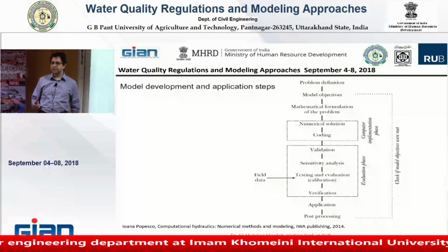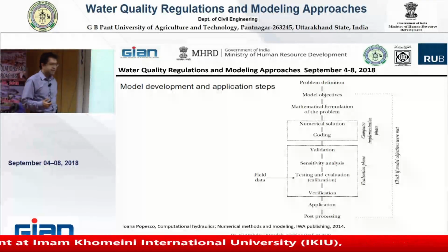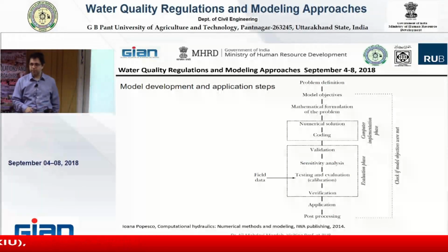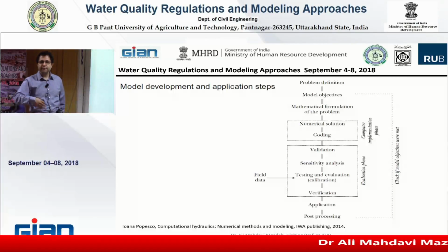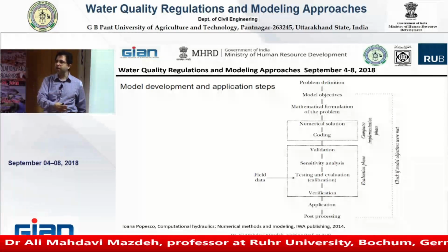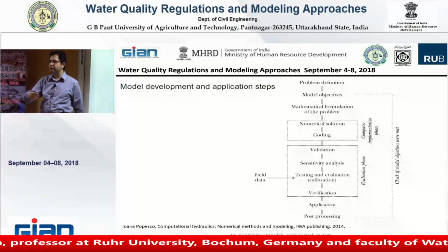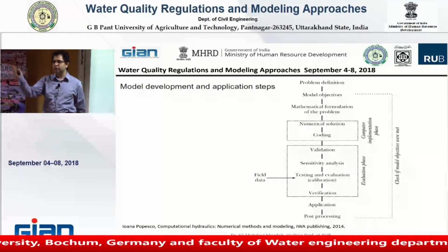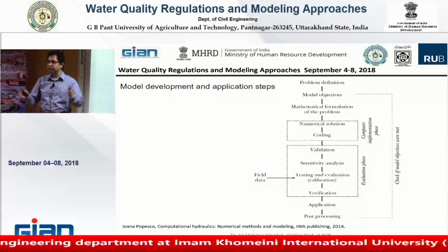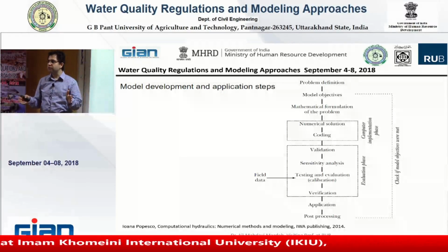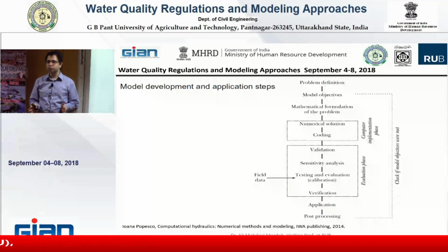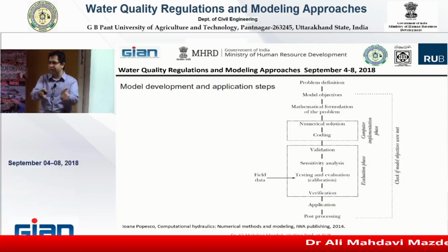now you must test if it can always make a good answer or not. This is the verification part, because you want to say to the water authority that from now on they can use this model to understand how the pollutant changes in the groundwater. You must be sure, because when you calibrate with your data, the result of the model with that data is completely good, because you calibrated the model with this data.